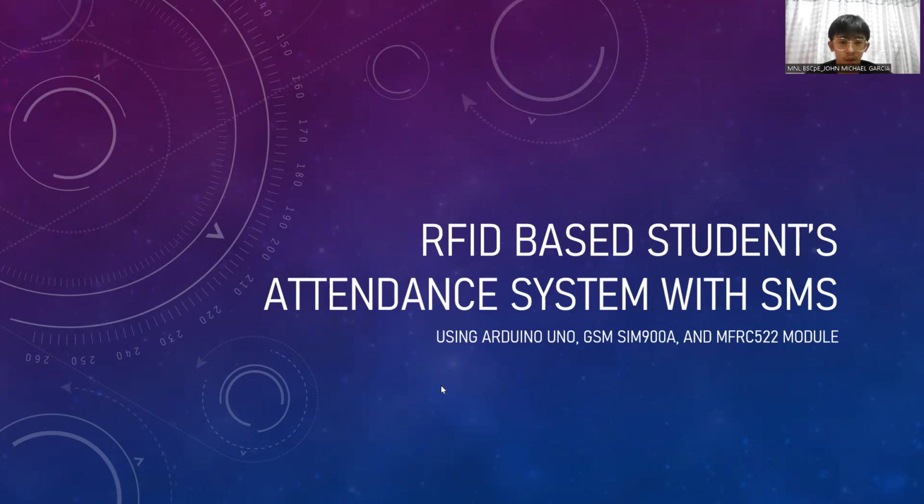Since I have quite knowledge relating to this automation system, what I can recommend for those who are trying to make one is that use a long-range RFID reader, at least 1 meter distance from the tag and reader, so that the whole process can be fully automated and the student or teacher will just have to walk past by the reader. Typically, they will be placed in entrances. So by this means, students' time in and out of the campus can be recorded and logged.